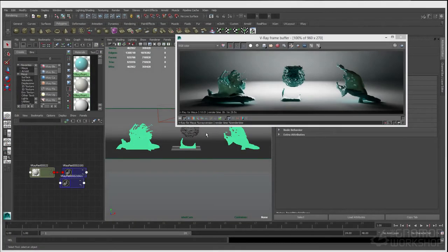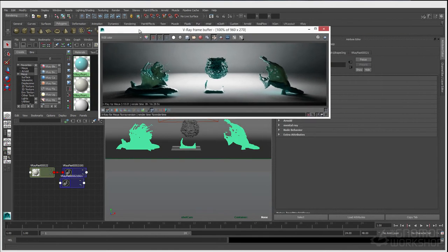In this chapter, we're going to be going over Vray Proxies. The idea of a Vray proxy is that it is a ready-to-render mesh that can live on your hard drive instead of living inside of your Maya scene. They're very effective, and now in version 3 of Vray, they can also accept the Alembic format, which is awesome